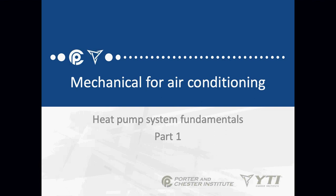Okay, so in other words, we raise our pressure, which raises our boiling point on the condenser, and we lower our pressure, which lowers our boiling point on the evaporator. So all we're doing is changing our pressures around. Is there any reason why I couldn't do that in reverse?